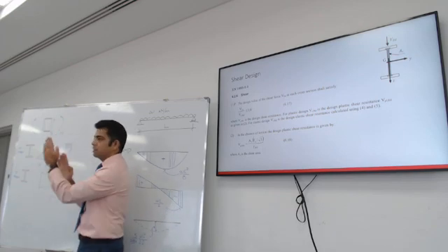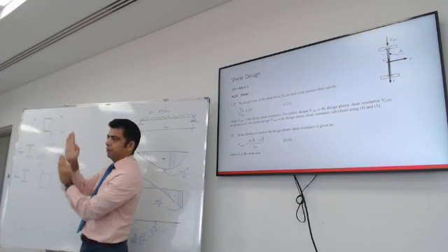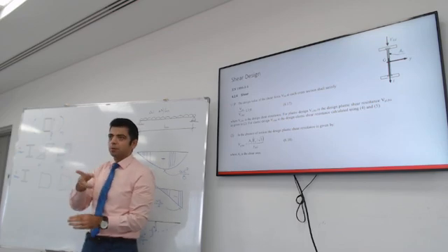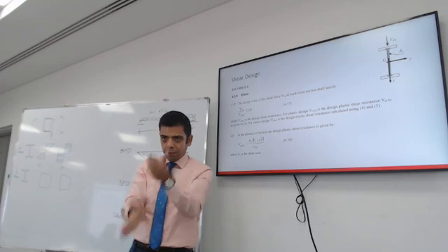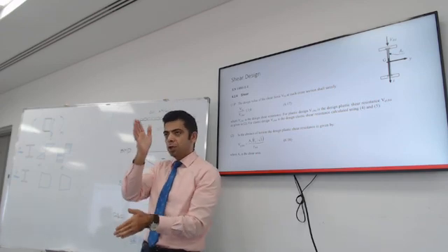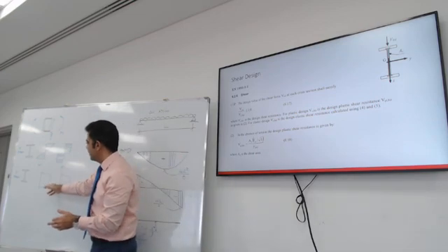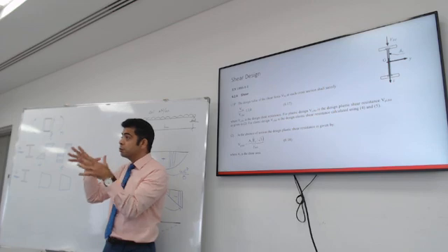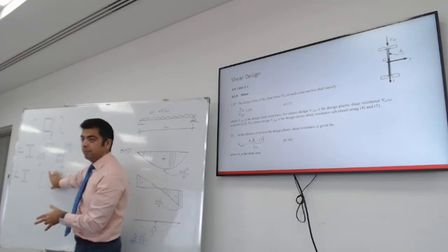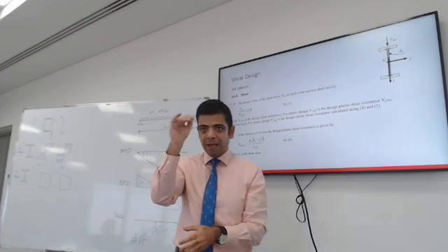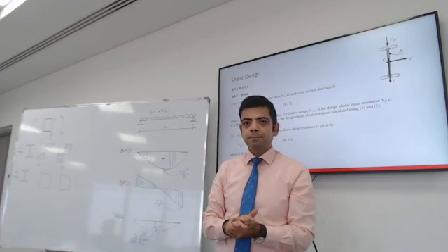The shear force is applying a vertical force Fy on it, trying to shear it. That's what scissors do. And this shear force introduces this stress distribution. Most of the stresses are on the web, the vertical part of the I.